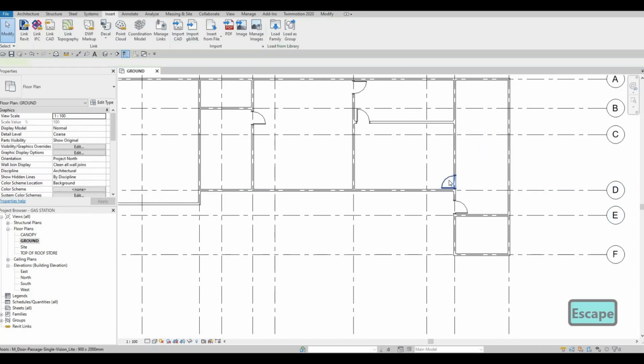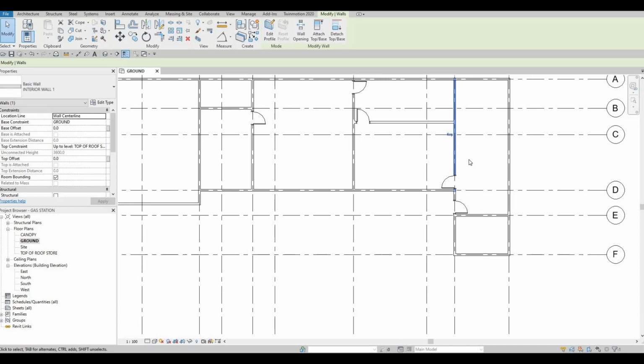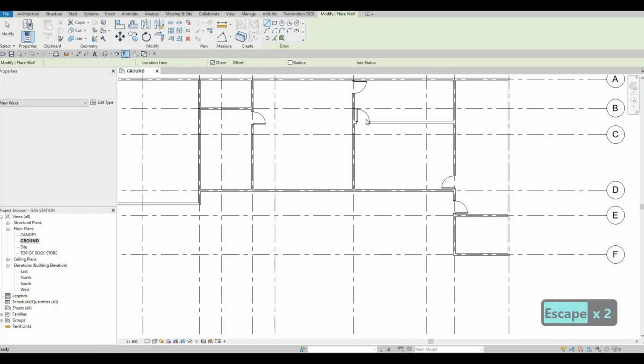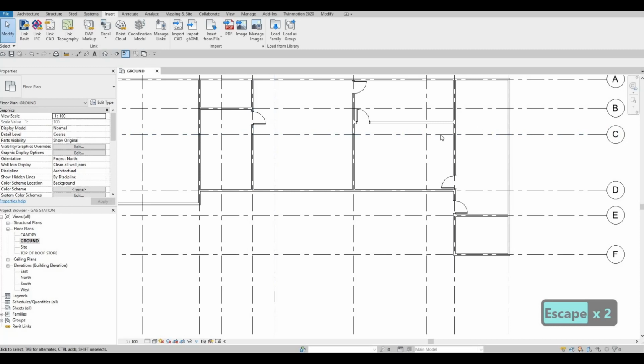And then now I'm just seeing we need to add the same walls and an interior wall. So it's easy for us to just select this one instead and then type in CS. So CS stands for create similar. It's basically if you have something that you already added before, you just need to select them and then type in CS and you'll be able to add them again instantly.